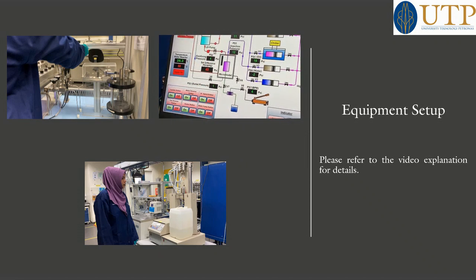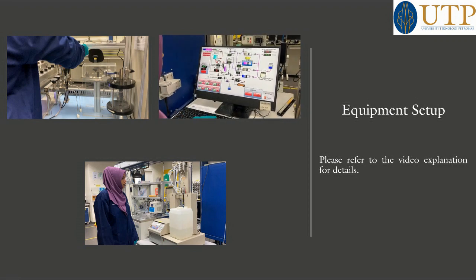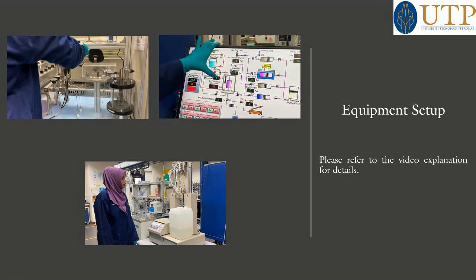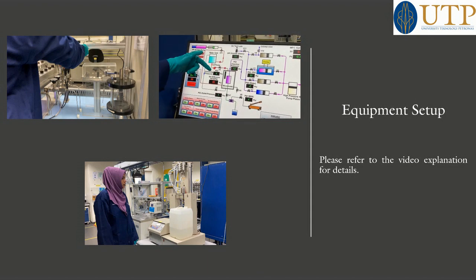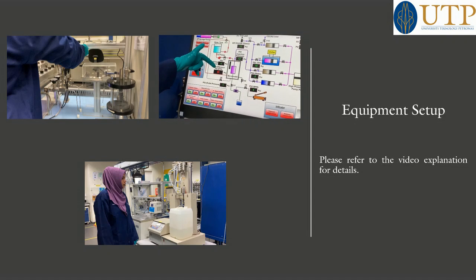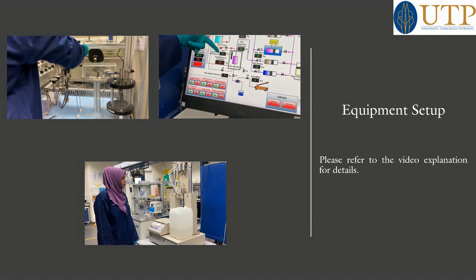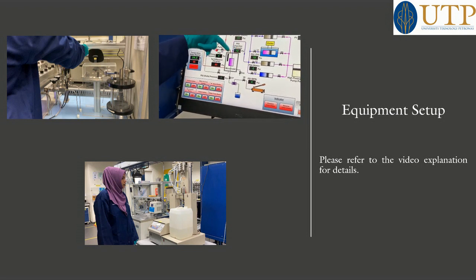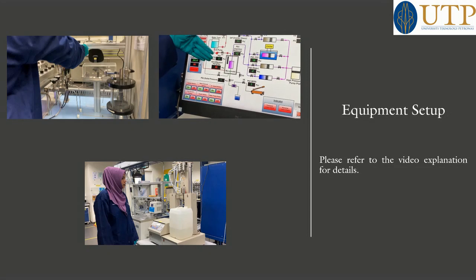In this software we also have to learn something. The confining pressure helps to maintain the pressure inside this Micromodel. Suppose we already set the difference between PS1 and PS2 as 40. That means the injection pressure and confining pressure differ by 40. So when my injection pressure is 12, my confining pressure will be 52.